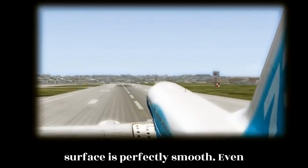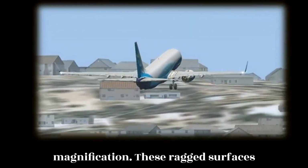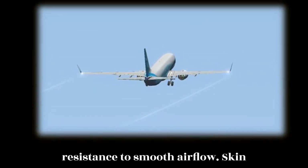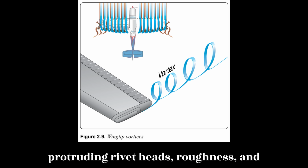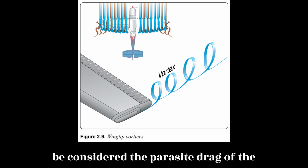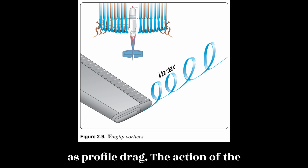No surface is perfectly smooth. Even machined surfaces have a ragged, uneven appearance when inspected under magnification. These ragged surfaces deflect the air near the surface, causing resistance to smooth airflow. Skin friction can be reduced by using glossy smooth finishes and eliminating protruding rivet heads, roughness, and other irregularities. Profile drag may be considered the parasite drag of the airfoil. The various components of parasite drag are all of the same nature as profile drag.